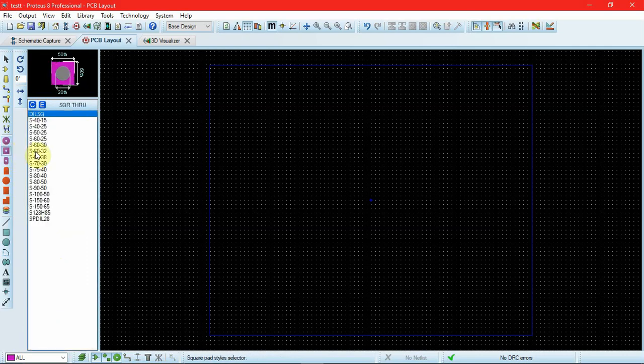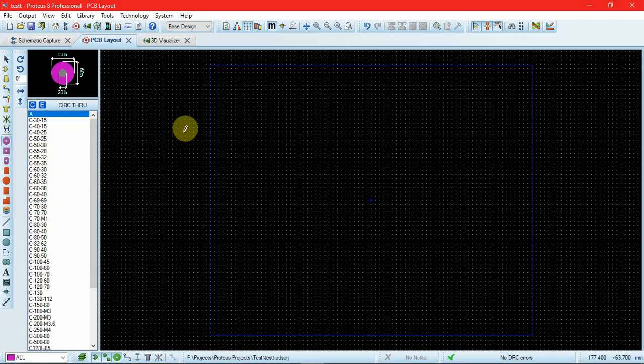These are the square and these are the DIL tracks. And then we also have pad modes for SMTs, surface mount technologies. We can have different pads depending on our needs. The component that we are making is a header for the ESP, so we'll require the circular pad modes as well as the square pad modes to define our first pin. So let's go with the circular first.